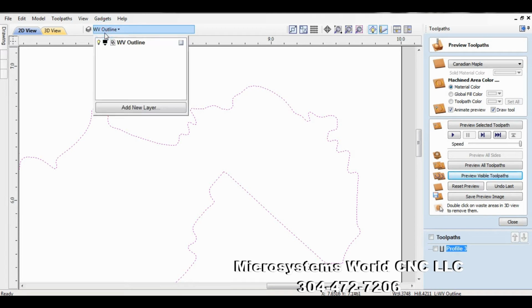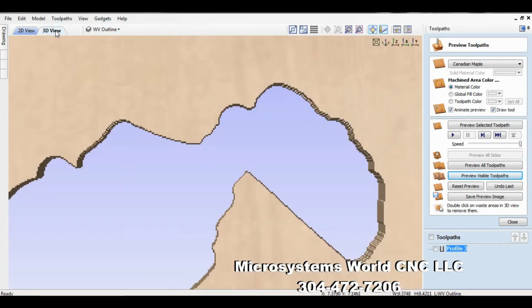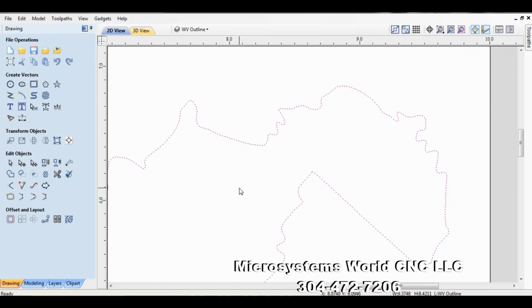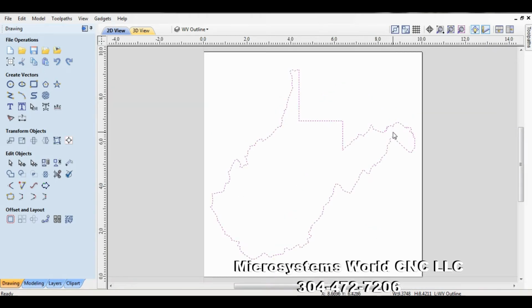In the 3D view, you can see that those don't really show up very well. So the only way that you can get those to show up better is to use a smaller diameter tool. And that's where using something like my angle offset tool would help. And even though I'm not using a V-bit, I can still use that tool. And I'll pull it up and show you.